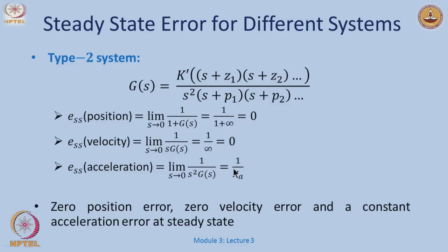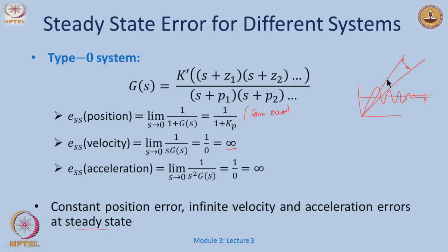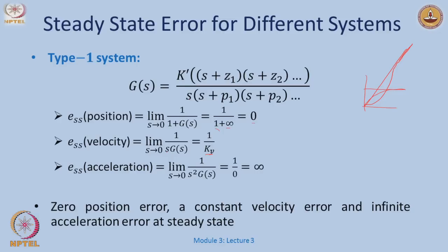Okay. Now, suppose I give a little problem saying take a type 0 system and make the position error 0. What would I do? Remembering all this theory, I would just put an integrator, or add a pole at the origin. This is a system which has more poles than zeros, so I can possibly always realize this, and I can just put it here. Can this be done, can this not be done, or can this be done with some care? We will see all those things. But these are the design specifications which would be given to us, and then we can see that these errors can be quantified just based on the type of signals which we are tracking and the type of the system. So, having an integrator in my system or having a pole at the origin gives a little more hope in designing the system.